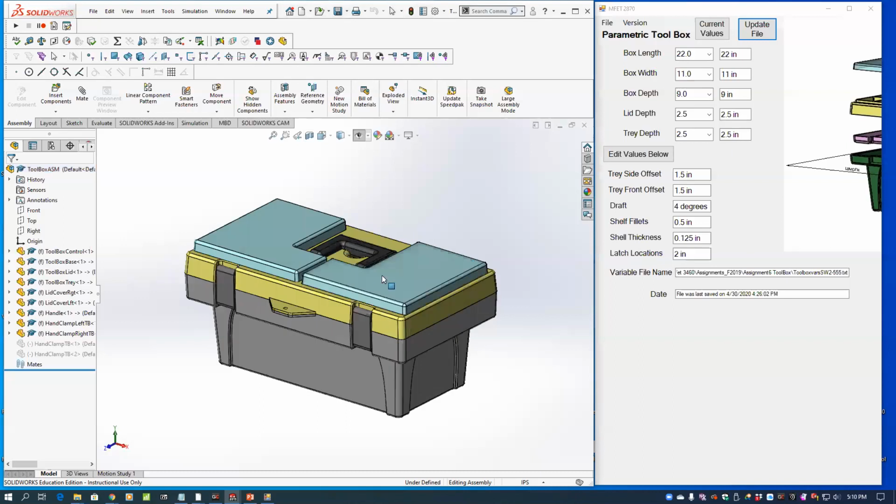And of course the handle and these covers. To help illustrate the power of derived sketches, I've assigned a number of the dimensions to variables in the equation list. Those variables are also linked to an external text file, so I can control those dimensions from outside SolidWorks, such as a Visual Basic program. That file could also be written to by Excel or even Notepad.